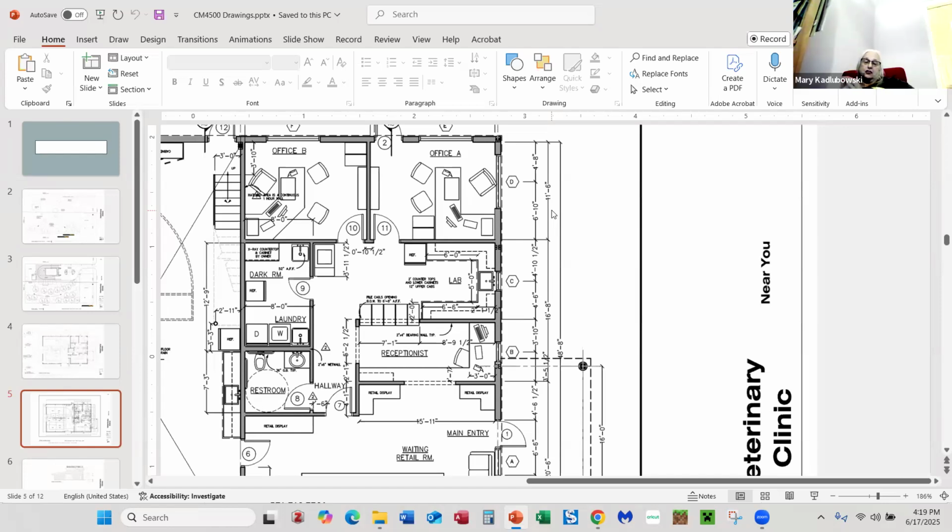That's as far as you need to go with your electrical plan. Don't worry about parking lot lighting. Don't worry about lighting the corral or the driveway or anything else. Do we need to show the running of the wires, like with the little arches and to the electrical box? No, but you do need to show where they're connected, the lights connected to the switches, so we know which switch goes to which light.